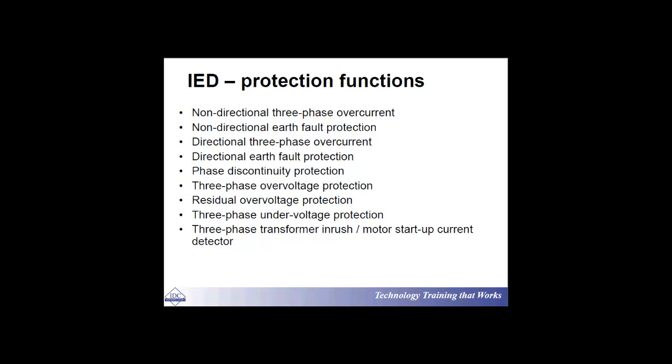It can also be equipped with over-under voltage and over-under frequency devices, overload devices, for example, in terms of transformer inrush or motor restart. That could be an example of a protection IED. I can define a lot more functions. That was just an example.